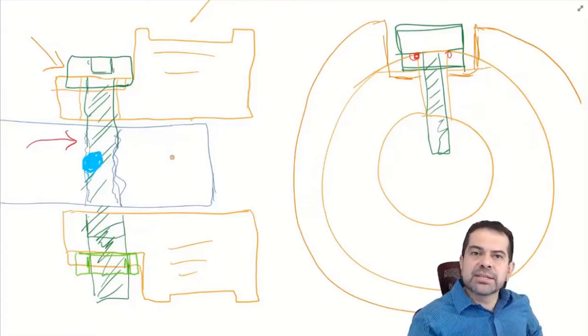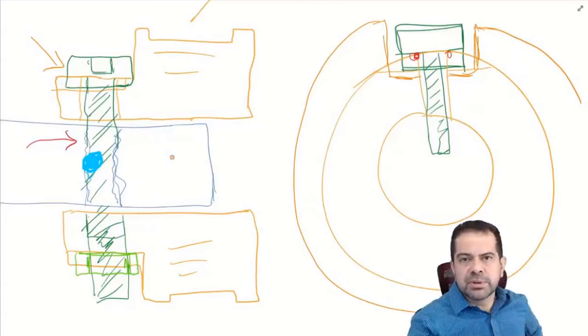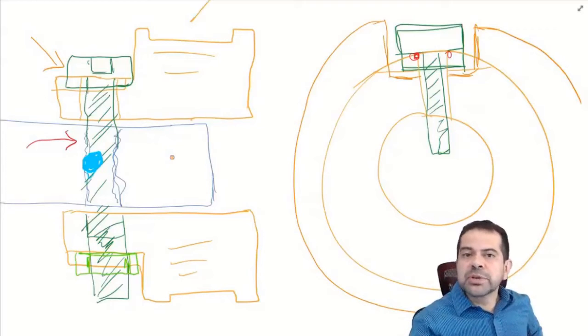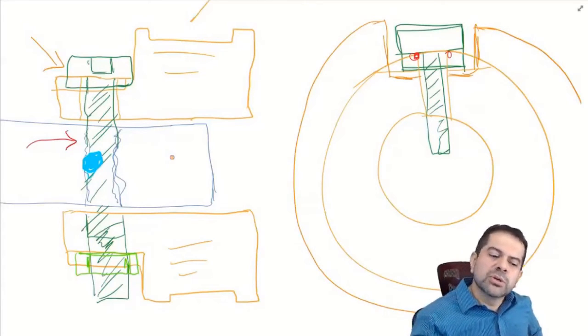Maybe it's okay, since we're talking about custom applications, not large quantities. Maybe it's acceptable, maybe not. But I have been told, when I implement this approach, they point out, just keep in mind, the motor shaft is probably hardened. We're not sure if we can do it. They always tell me that we're not sure if we can do it, and then they always do it. So it works. But if you're dealing in a situation where the shaft material is just too hard, it may be inconvenient to drill and tap through the shaft.